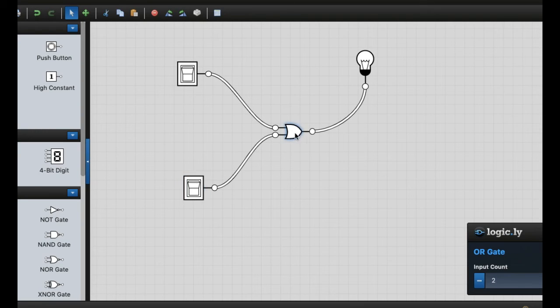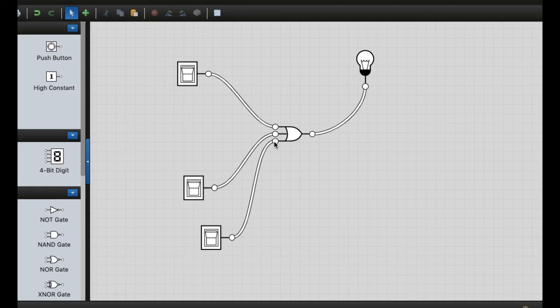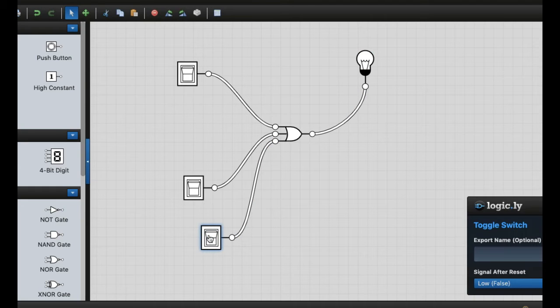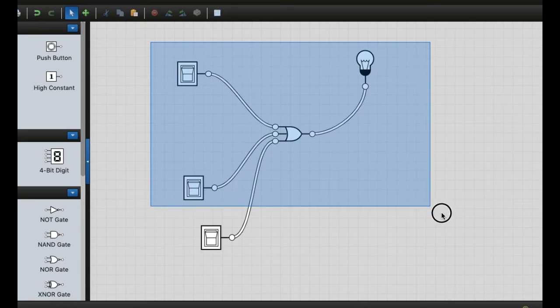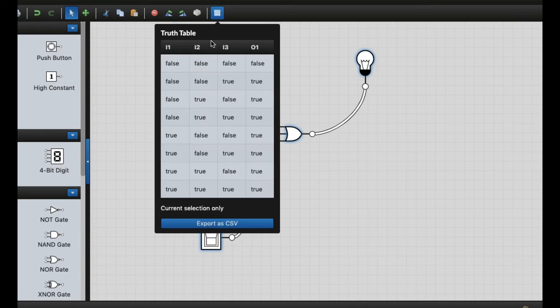So this is similar if you have even 3 inputs, you can see a similar result. If any one of these switches is turned on, then you can see it will start working. Means if all are off, then only this is off. What is the logic of AND? AND logic is where you have all the inputs present, or all the inputs 1, then only you can produce output 1. So what is the OR logic? If you have all the inputs 0 or false, then only it becomes false. All the inputs false, then only it's false.